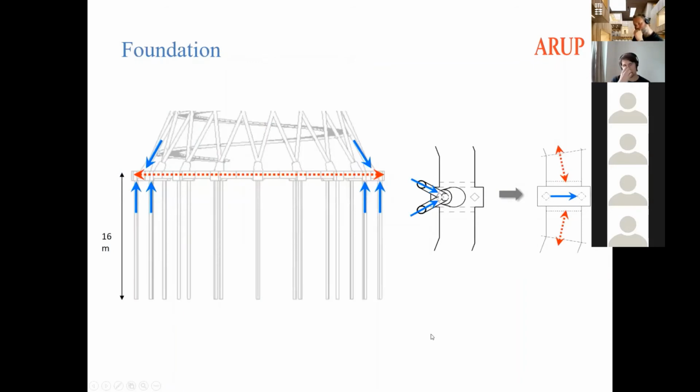Finally, I'll just mention a little bit about the concrete, which is basically everything below the steel structure. So if we start from the top, we have the load going into the concrete plinths, which are these inclined cone elements. And then we have the pile cap. And then in between the pile caps, we have the concrete ring beam. And then we have the driven bearing piles underneath the pile cap.